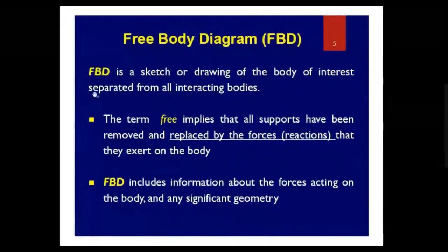Now, a free body diagram is a sketch or a drawing of a body of interest separated from all interacting bodies. The term free implies that all the supports have been removed and replaced by forces or reactions that they exert on the body. So a free body diagram includes all the information about the forces acting on a body and any significant geometry.